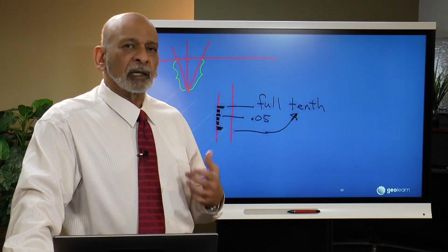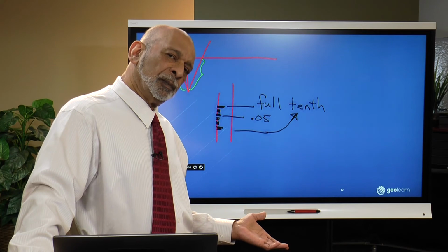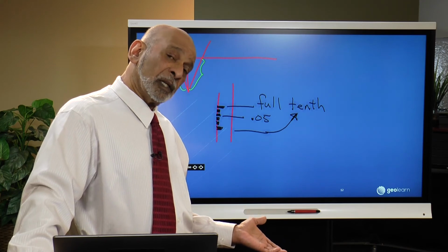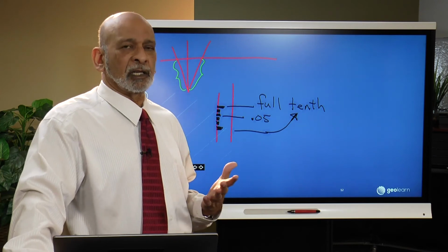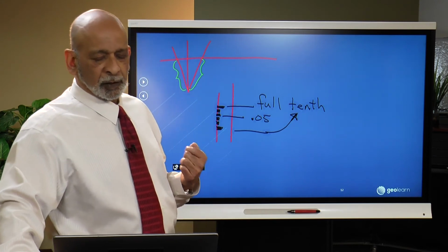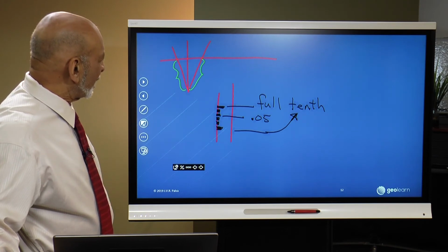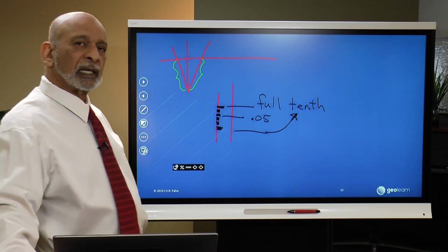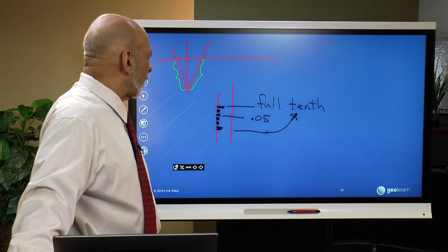It's a good idea to observe, take your eye away from the telescope, write it down or call it out, then look back in again and see if you get the same number. Especially when you're starting out, that's a very common mistake, to read the wrong number, which can lead to erroneous results. So always verify that.